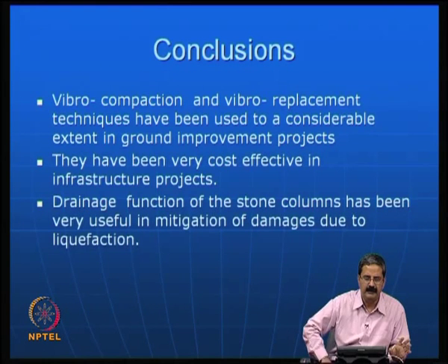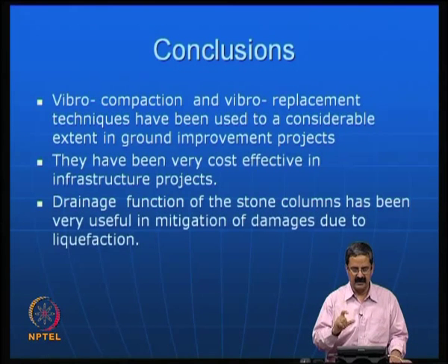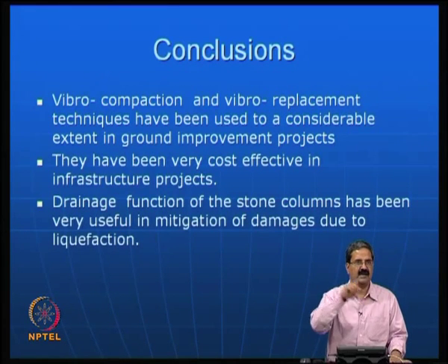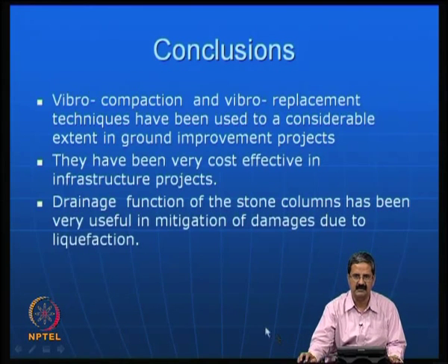What we discussed was about simple static loading, but you should even design the stone columns for earthquake conditions, where you consider how many cycles it can withstand. For example, how much pore pressure it can dissipate, because earthquake motion is always converted into an equivalent number of cycles of some standard loading. So one can design for how many cycles it can withstand, and one should do some more detailed studies on using stone columns and come out with proper measures.